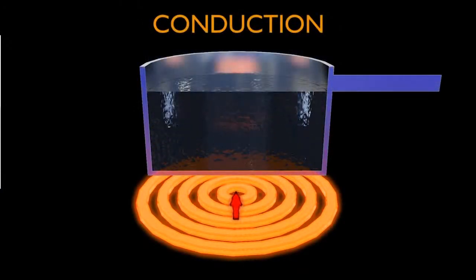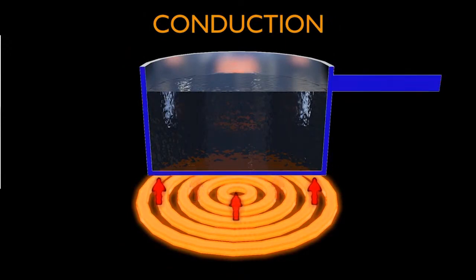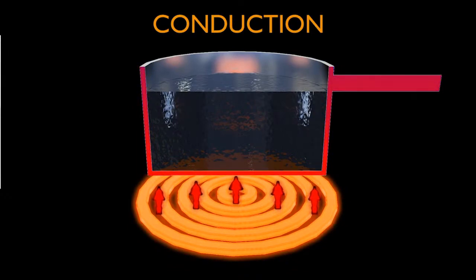Conduction. Conduction happens where two objects are in contact with each other, like the base of the pan sitting on the hot plate. This direct contact lets the heat flow from the warmer hot plate to the colder pan, either until the temperatures equalise or the pan is removed. Most building insulation boards, such as mineral fibre or polyurethane, for example, work to resist heat transfer by conduction.